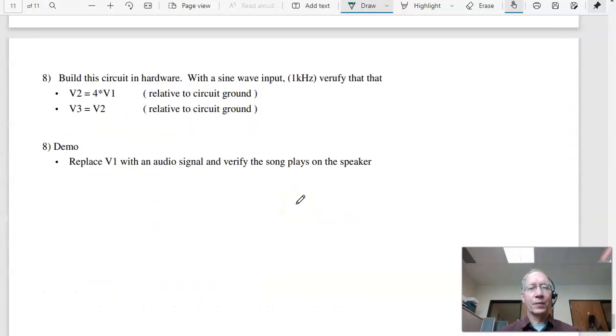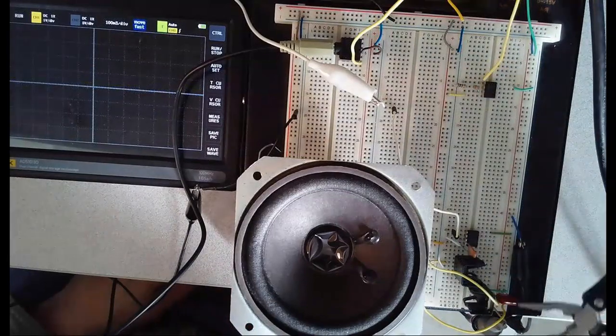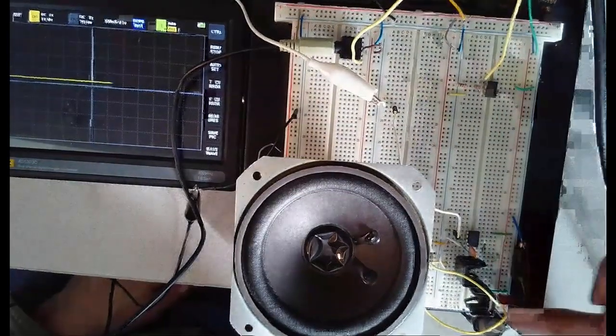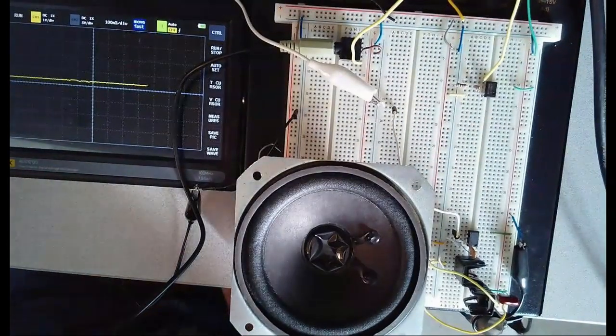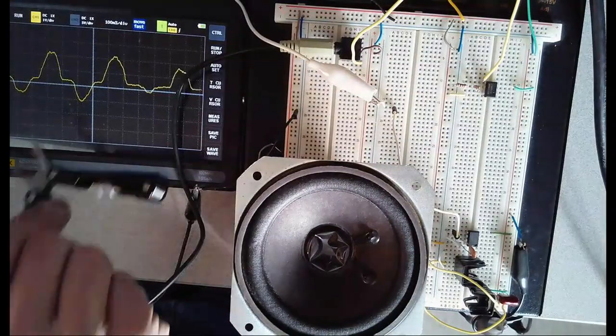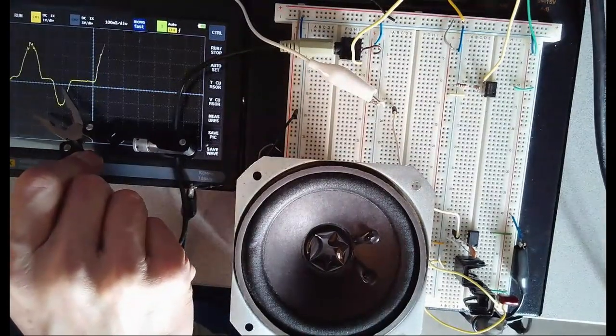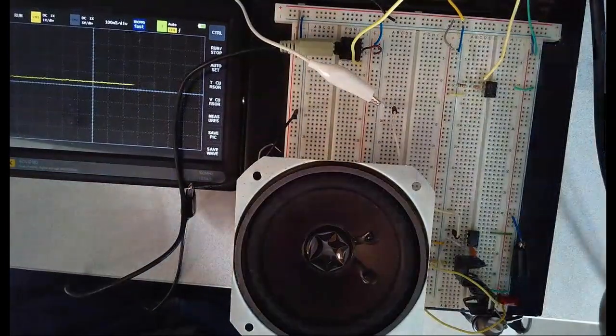Then in hardware, we can give a demo. Here's a couple examples of a push-pull amplifier. Now right here I've got the NPN and PNP. Currently just have a low frequency sine wave driving it directly. So as you go forward and back, you can see the crossover distortion, that little elbow right there. That convinces me that the push-pull is working.